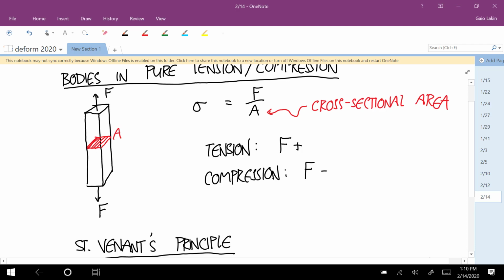If instead of being point loads, those were uniform distributed loads, so this force F was applied uniformly over the whole top and over the whole bottom, then every point really would have that stress. That makes sense, I think. You can think of it in terms of the tractions and stuff, and you could calculate that. But the question is, if we go from the uniform distributed load to this point force, can we treat it like those loads are the same?